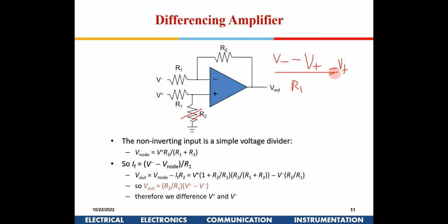No, this current is going to be V plus minus V out by R2. Right now, you have to keep R1 and R2 also the same. Yes, in that case, yeah. Then there will be no gain. It will be unity. Okay. Right. Correct.